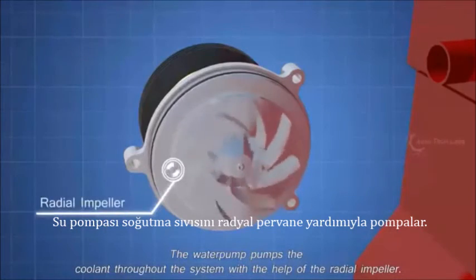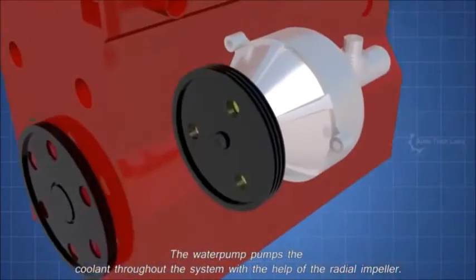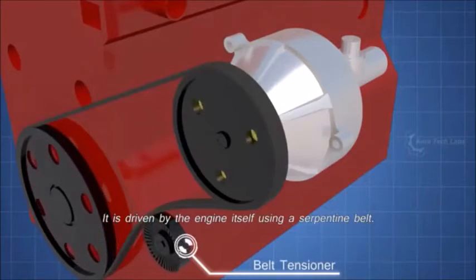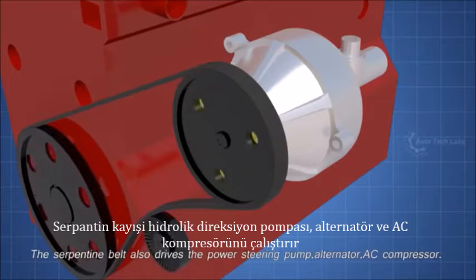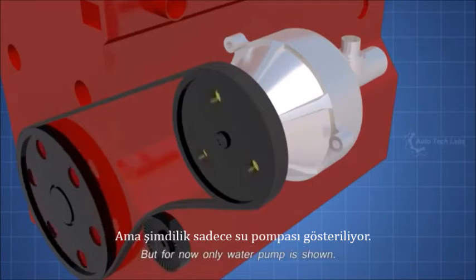The water pump pumps the coolant throughout the system with the help of the radial impeller. It is driven by the engine itself, using a serpentine belt. The serpentine belt also drives the power steering pump, alternator, and AC compressor. But for now only the water pump is shown.